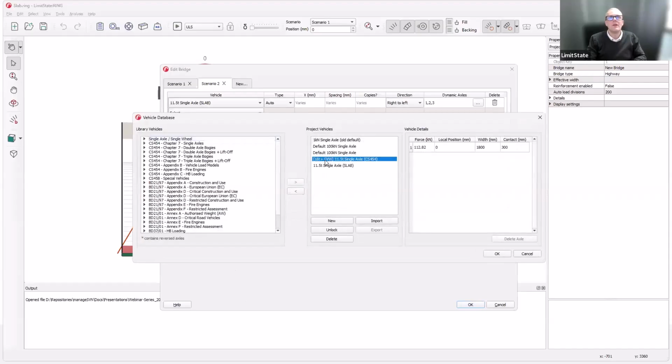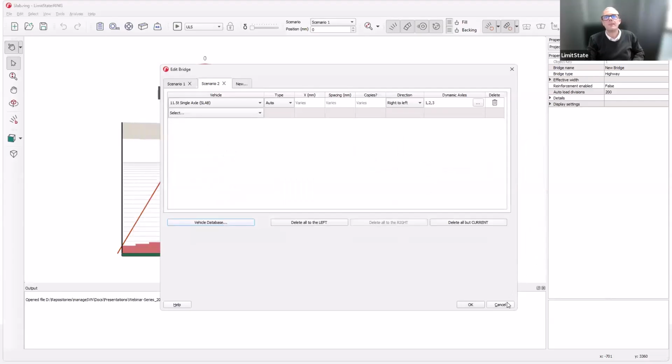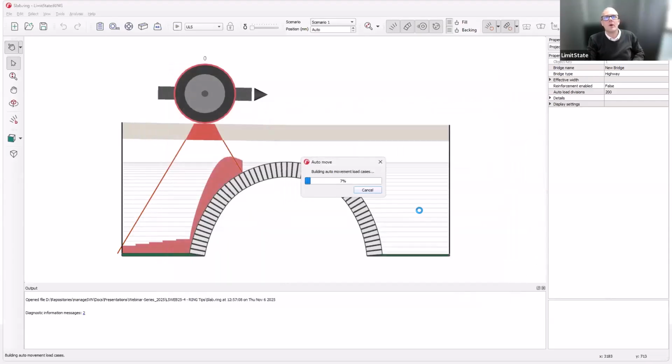We look in the vehicle database here. That's the single load. And then the slab version, we have taken the span, divided it by 6, added extra axles at those locations, and then divided up the loading into 3. So 25%, 50% over the middle, and then 25% again. We'll then solve both these problems.